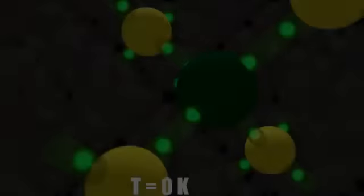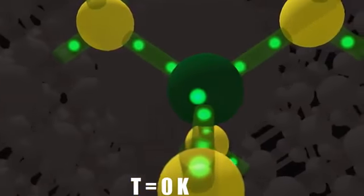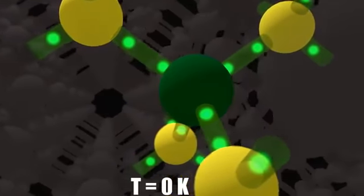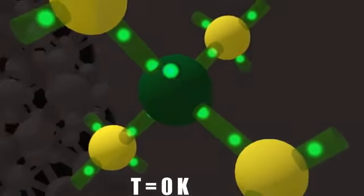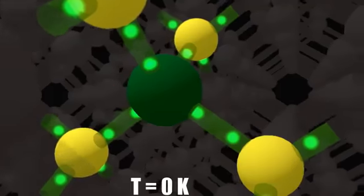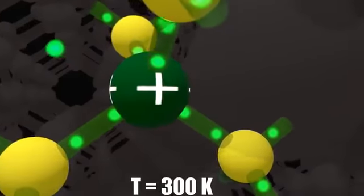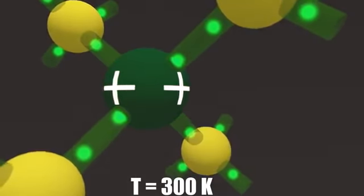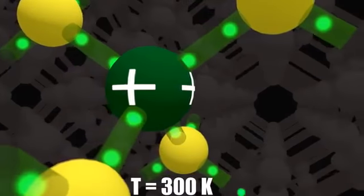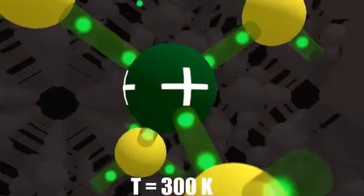Impurities can be introduced into the semiconductor, substituting atoms of a different atomic species for the silicon atoms. If the new atom has 5 electrons in its outer shell, 4 of them will replace the 4 electron bonds of silicon. The extra electron will be loosely bound to the impurity. At room temperature, this 5th electron is liberated from its original atom, becoming a conduction electron. Consequently, the impurity acquires a positive charge.